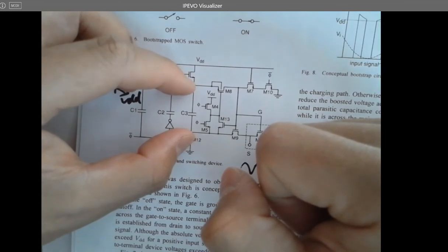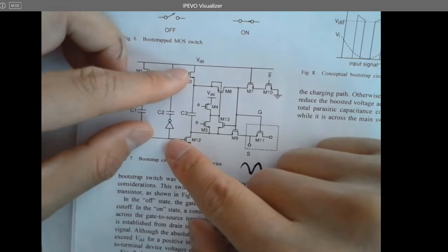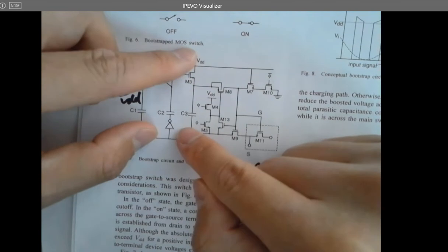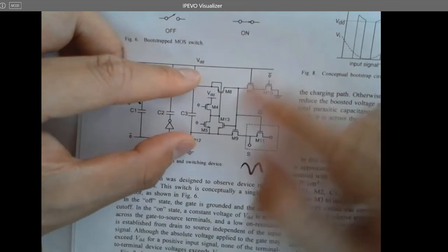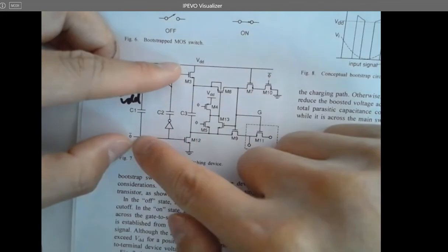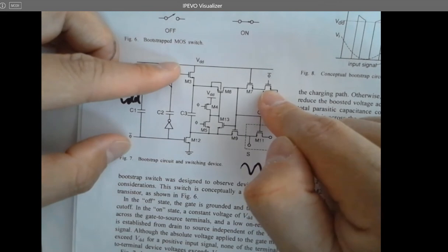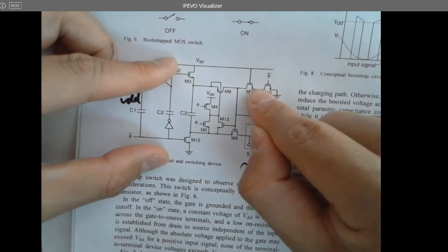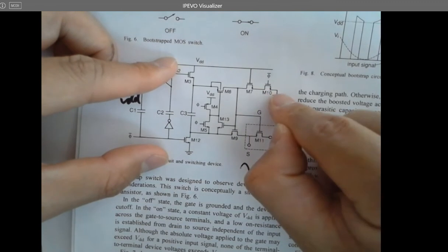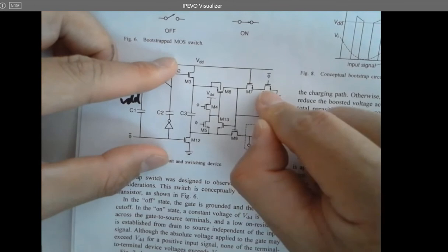VDD. All right. Now let's look at this point. Whenever this is high, remember I still turn this to on, turn on, pull, charge up, right? Still in the same cycle, because this is the same signal as this one. So this is also on, right? So what's happening is this is on, so the ground will be passed to here. This is always on, so the ground signal will be passed to this point. So it's going to pull this to ground.